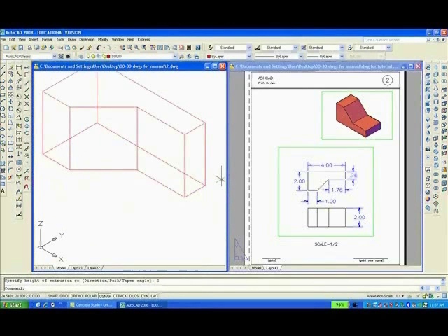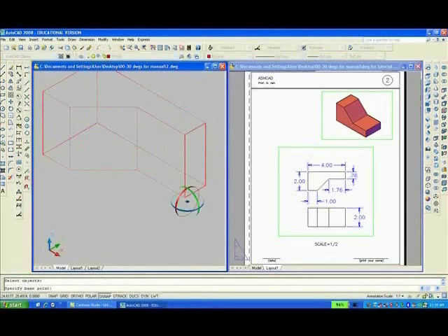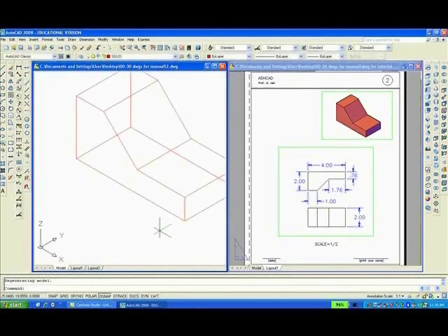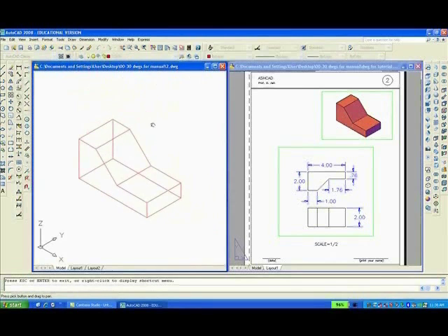Then you'll go to 3D rotate, which is over here. You'll select the object, you pick any point, we'll select the red axis, it turns gold. We want this object to rotate clockwise, so it'll have to be a negative number, -90, enter. And using Zoom Real Time, shrink it down and pan to center it. That's what the object is going to look like.